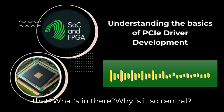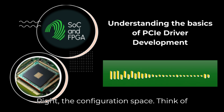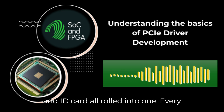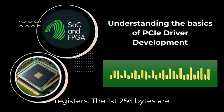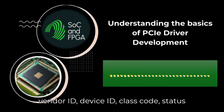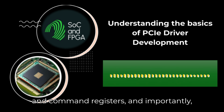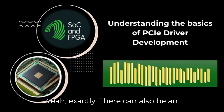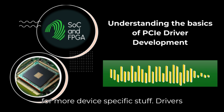Now, we keep mentioning the configuration space. Can you elaborate on that? What's in there? Why is it so central? Right, the configuration space. Think of it as the device's built-in control panel and ID card all rolled into one. Every PCIe device has a standardized block of registers. The first 256 bytes are standard, containing things like the vendor ID, device ID, class code, status and command registers, and importantly, the BARs, the base address registers. Exactly. There can also be an extended configuration space up to 4KB for more device-specific stuff.